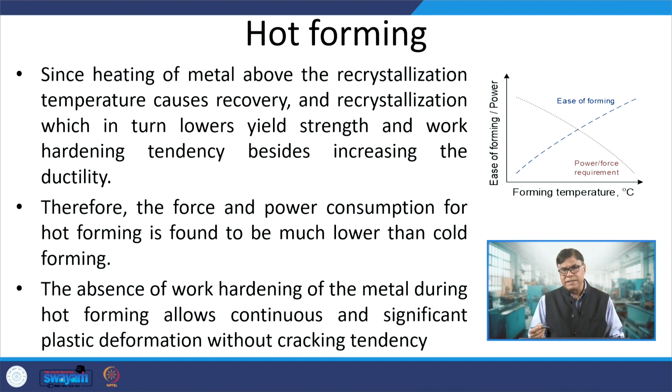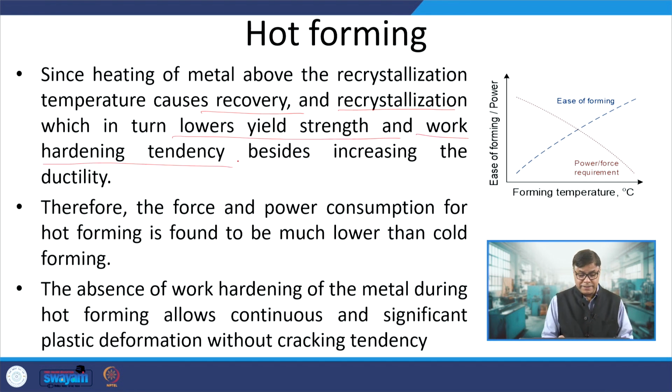When the metal is heated above the recrystallization temperature, it facilitates the recovery and recrystallization during the deformation itself. That is called dynamic recovery and dynamic recrystallization, which in turn lowers the yield strength and work hardening tendency besides increasing the ductility.